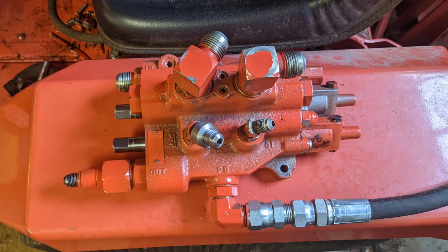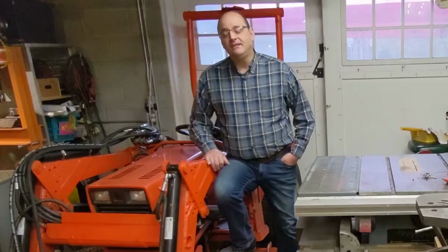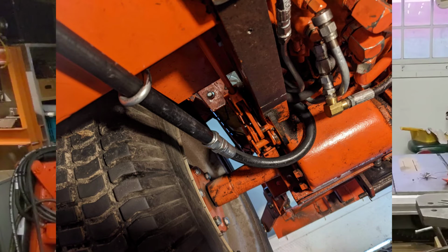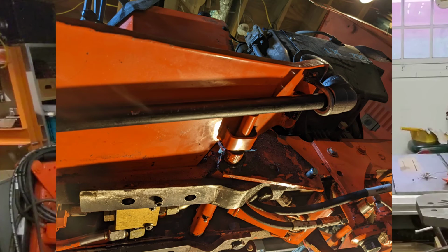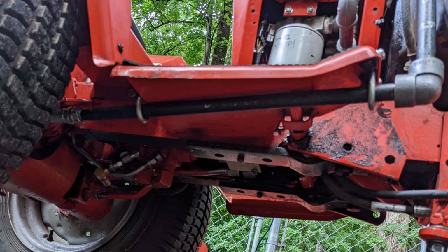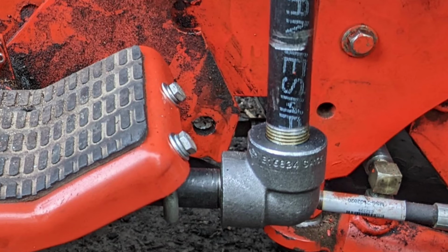For the high pressure supply side, I'll come out of the travel control valve with a short hose that'll just provide some vibration damping and make it easy to get the line to turn and twist down and out of that tight space up in there by the frame rail. From there, I'll run standard steel half-inch NPT pipe joined with special purpose 4000 psi rated carbon steel pipe fittings.